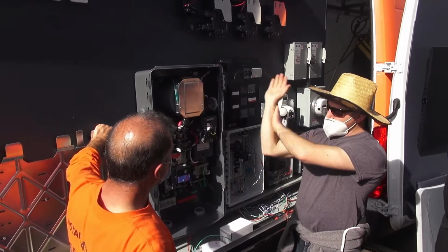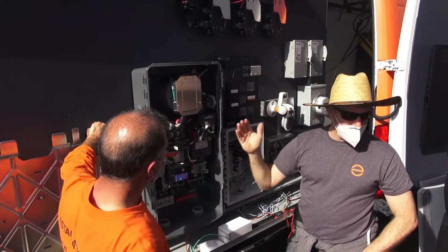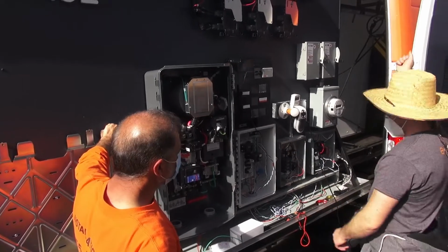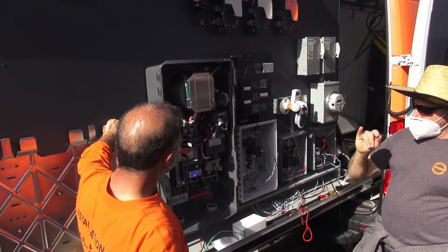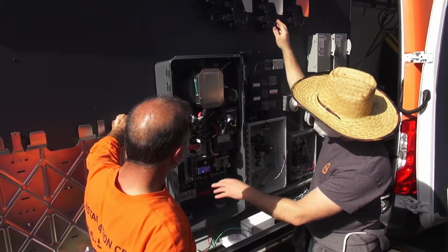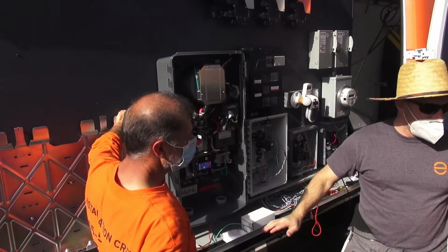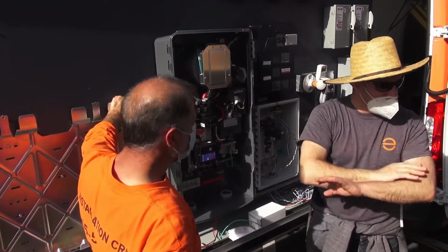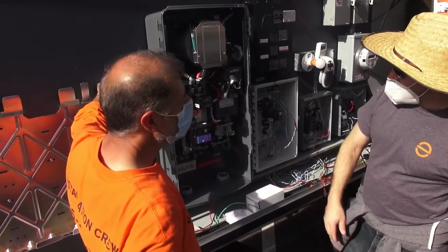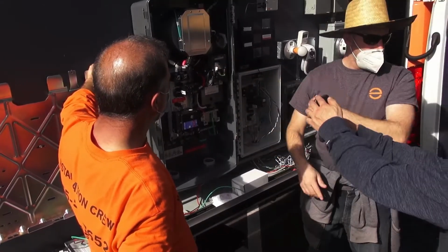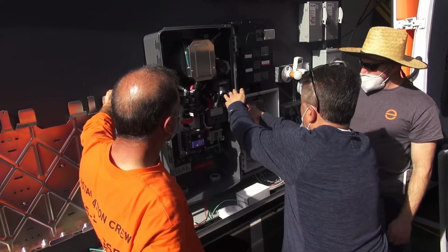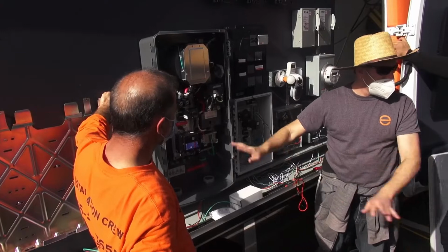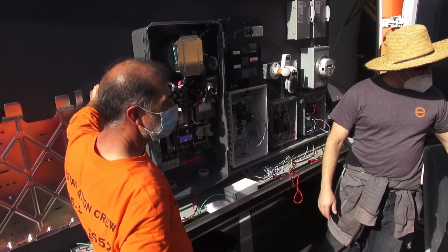If you accidentally push the switch to the left, or if you leave it to the left, and you go, oh, that's why it didn't work later when I did my testing, you have to remember that you have to turn everything off for at least a minute, because there are capacitors and things in here. You need to completely empty those out. So look, somebody made a mistake. They powered it on. You come over here, you turn everything off. I want no power anywhere. Just completely de-energized.